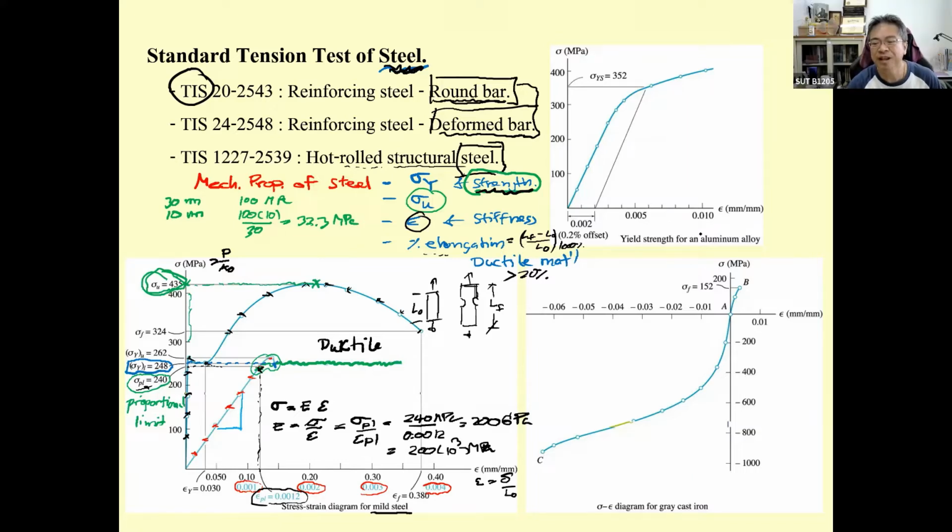And if we come to the aluminum alloy and do the test, the aluminum alloy is a kind of non-ferrous material. Actually, it is supposed to have very large deformation, such as this one. The strain is very large. This one didn't have this kind of yielding. The steel has it very clearly.